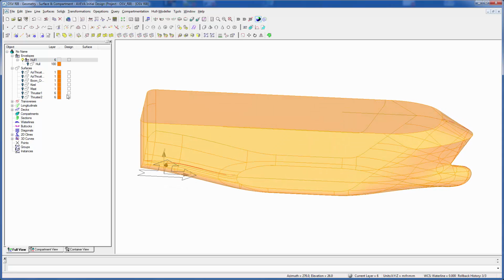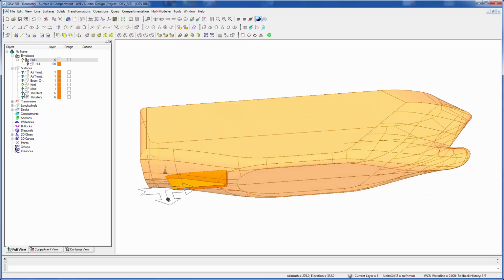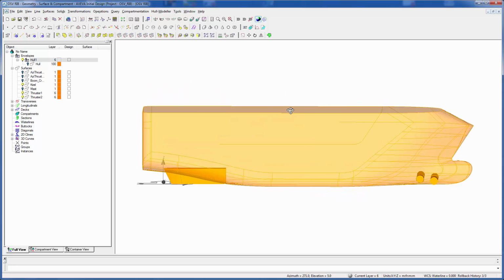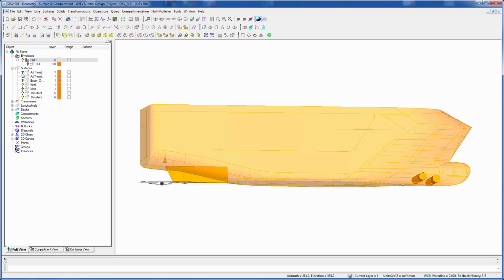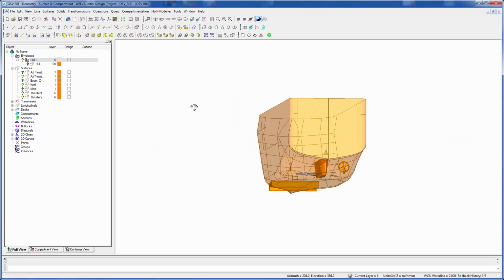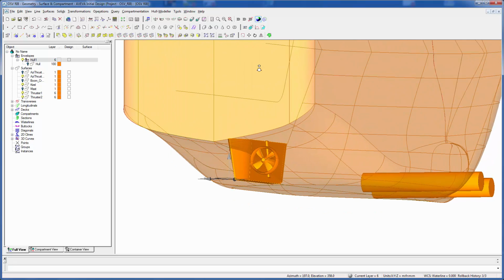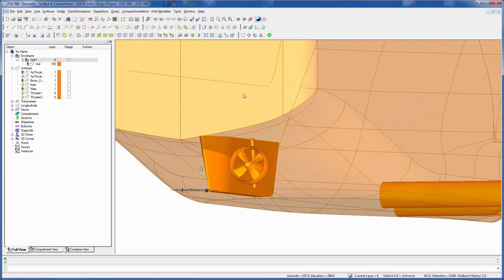This particular one is going to get some appendages added to it. We could add a skeg keel and some thruster tubes. We can use pretty much any shape you want. We do have some azimuthing thrusters here as well. We'll zoom in on them. So we can use some volumes that we can design to take up volumes for the hydrostatics. And these have been designed in the software itself, and to preempt that, we'll have a look at creating some simple shapes like appendages.